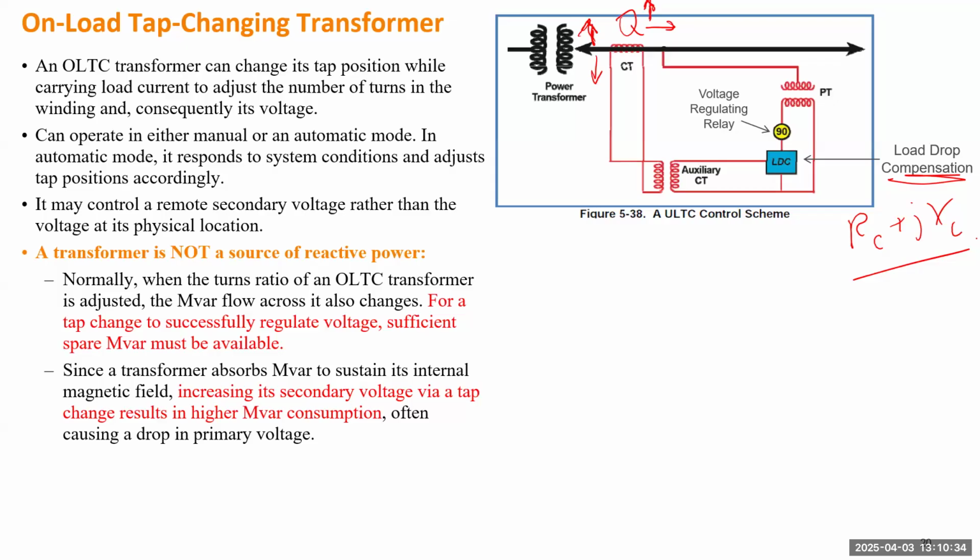In order to really explain what happened, we can wait until the voltage stability session, because that will cause some bifurcation issue, which means the direction of the control actually changes, but the controller doesn't know. So if the operator believes the primary side on the left-hand side is not strong enough, you need to disable this control manually, or you have some other algorithm to decide when to disable the tap changing transformer. Under normal conditions, it does give you voltage regulation, but under emergency conditions, they are usually the first thing you need to disable under voltage stability concerns.